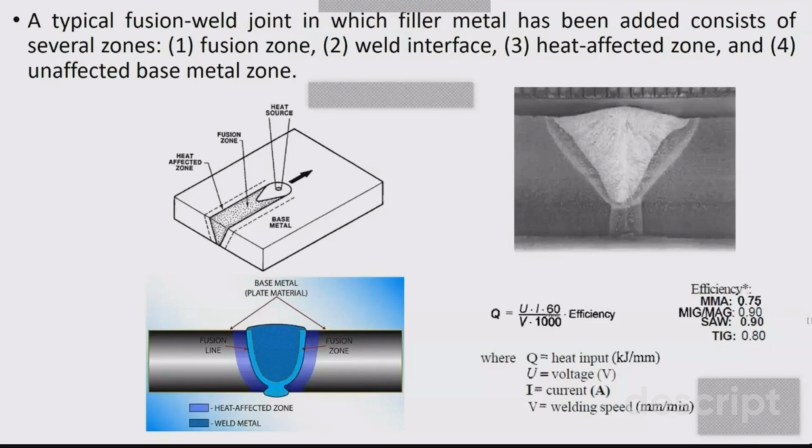However, in the case of the TIG welding process, in most books or engineering research papers, you can observe it maximum up to 60%. Similarly, in submerged arc welding, you can reach up to 80%. In MIG and MAG welding, you reach up to 70%, and in manual metal arc welding, this is also very low, reaching up to 50 to 60%. So these are the efficiencies which have been calculated under very ideal conditions or with the help of some correlations. But in actual welding conditions, it is very, very difficult to achieve this much efficiency.